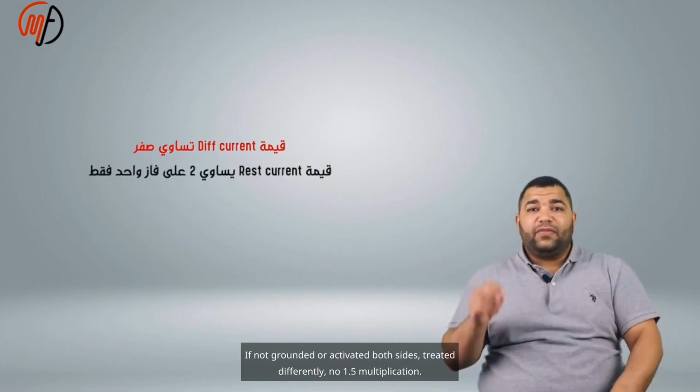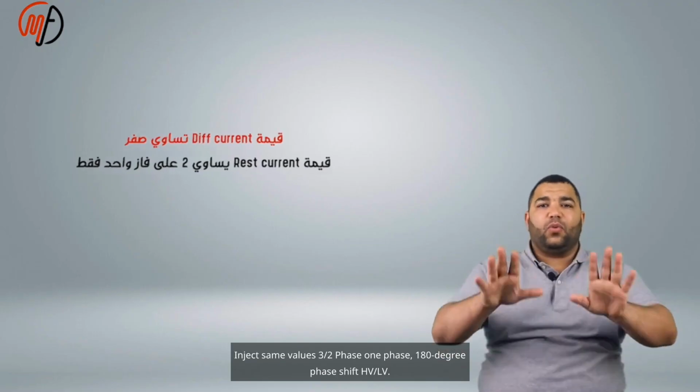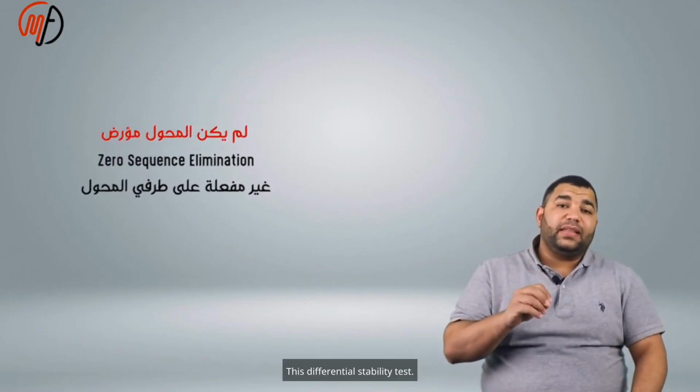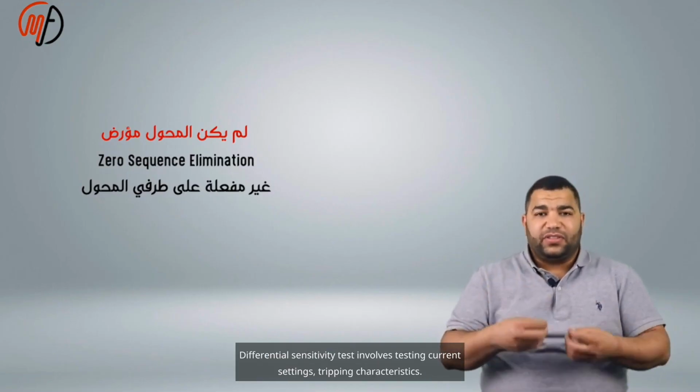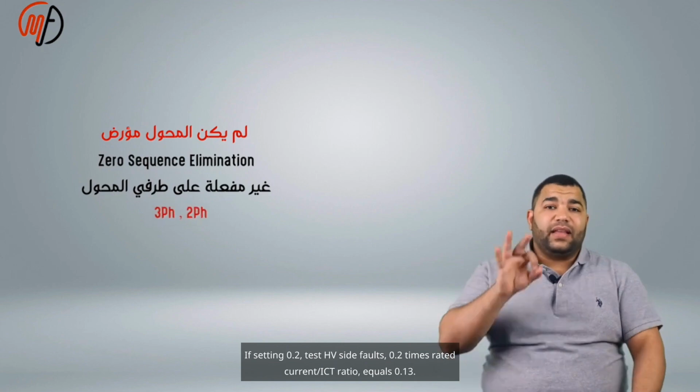Both sides are treated differently. No 1.5 multiplication. Inject the same values for 3-phase, 2-phase and 1-phase, with a 180-degree phase shift between HV and LV. This is the differential stability test. The differential sensitivity test involves testing current settings and tripping characteristics. If the setting is 0.2, test HV side faults.